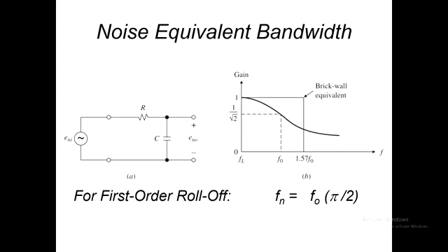We can characterise it, and we can characterise the filtering process, the way it treats noise, by thinking of a noise equivalent bandwidth as if it was a square flat filter. And the way to do that is imagine how much gets above the signal bandwidth. This is F0, the nominal 3 dB point that we use for signals.